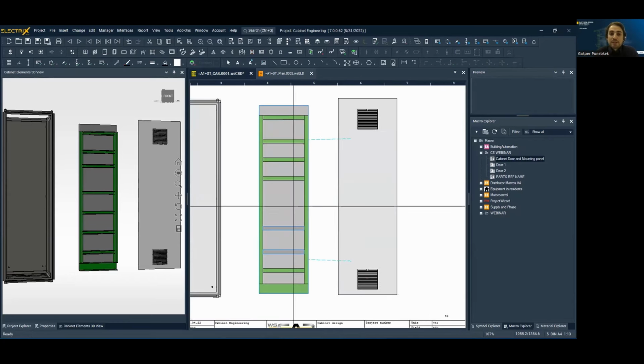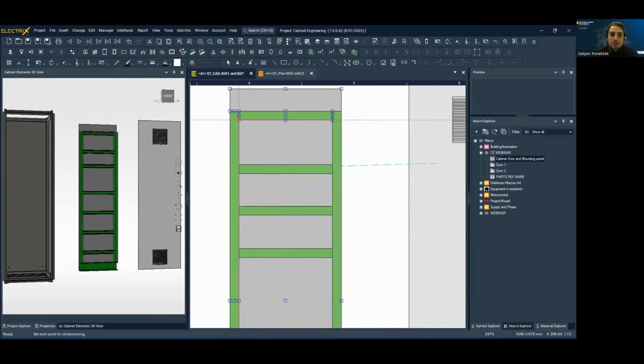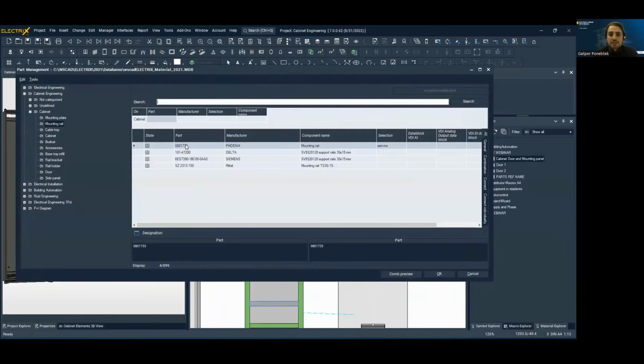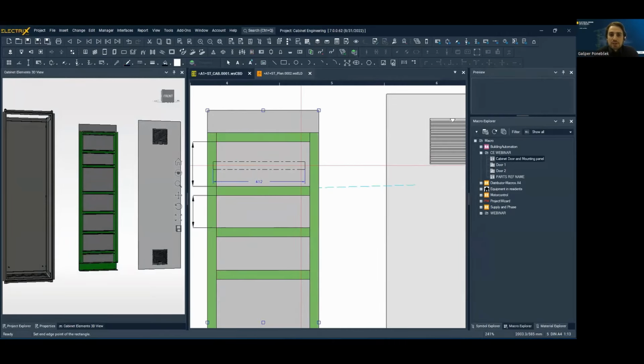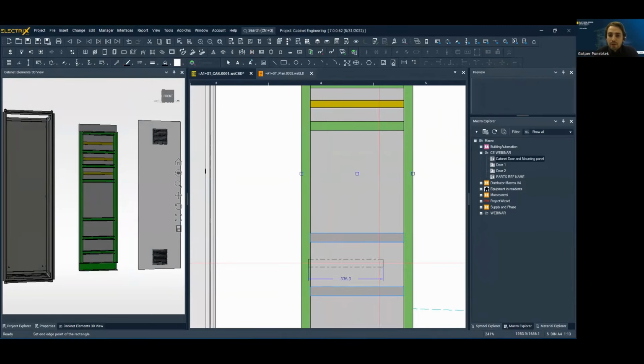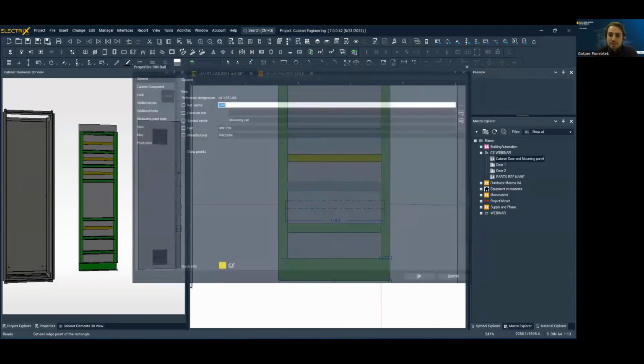So we can insert some measures also here that we exactly know what are the measures. We will just insert some of them to see how to work with that. Let's say here, as before, it's 100 millimeters and 145. And what we have to do is also we have to insert some DIN rails from Phoenix, as you can see. And here you can see we don't need to be careful how to place these DIN rails. Because we have these alignment objects and we can actually place these DIN rails exactly in the middle of these two cable ducts. You can see later.